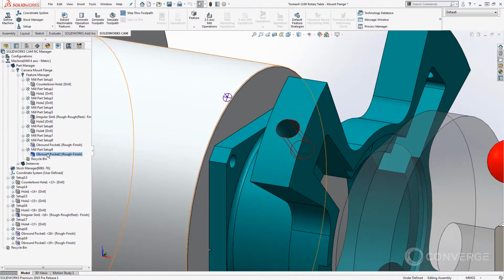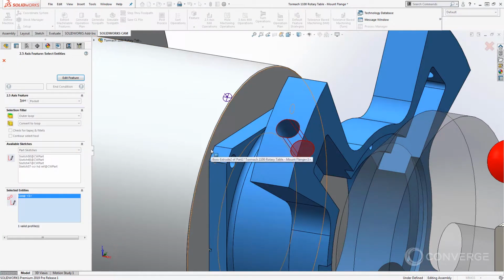When you're dealing with strict tolerances, you often might have to change the position of a hole based on some type of mid-tolerance value. In most cases, that'll require you to either manually modify the G-code or to go back and modify the model. But now, in 2019, we have an option that allows us to modify the toolpath location on the fly.